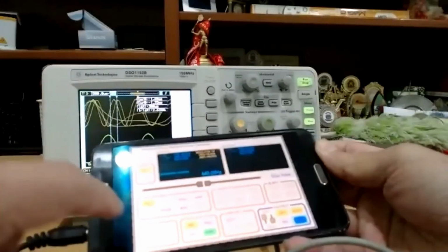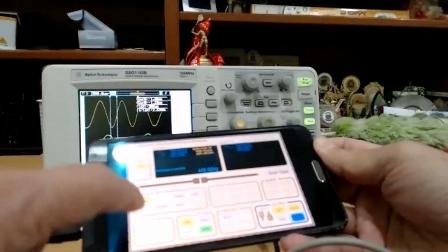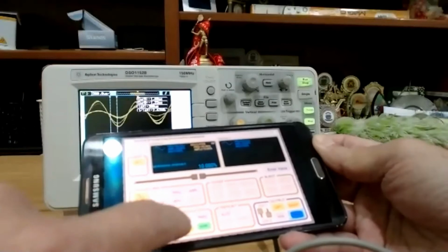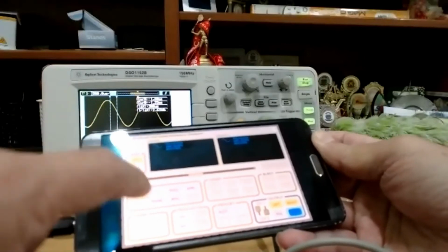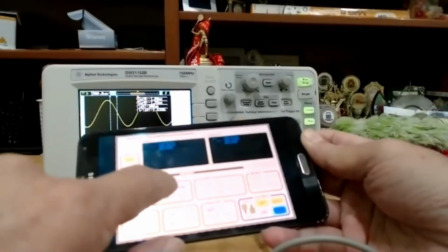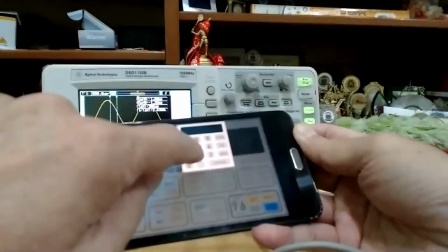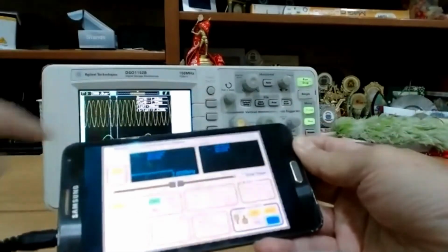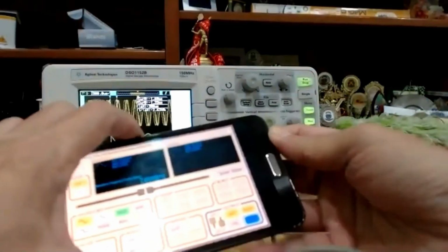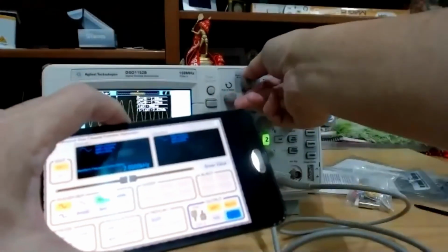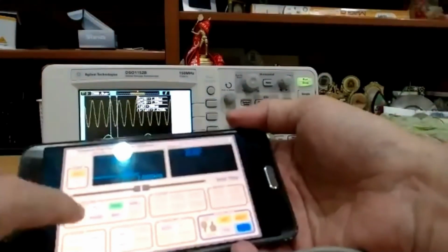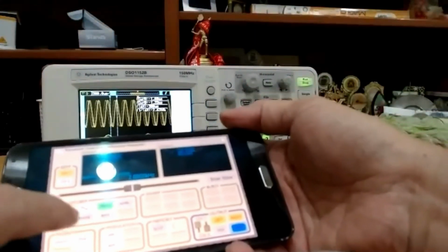This is the FM signal. Let me remove that FM. Okay, so I can change the frequency of one of the channels. I can enter a value, let's say 2K, and the frequency will change to 2 kilohertz. I can also change the phase information.